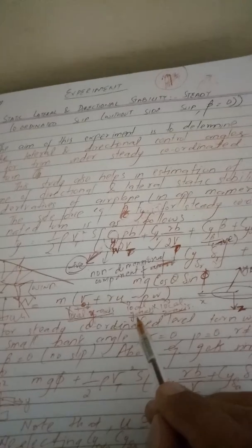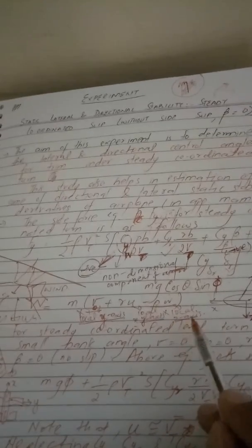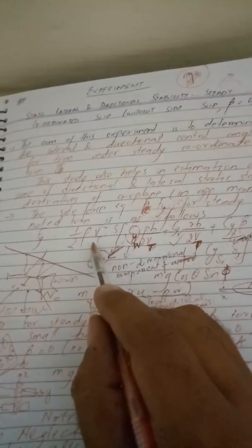So let's see, that is the v component, the local v component of total Vt, because v naught is at the local y-axis, and u is the local x-axis component of this Vt, and w is the local z-axis component of this Vt, which is the total velocity because of the turn.